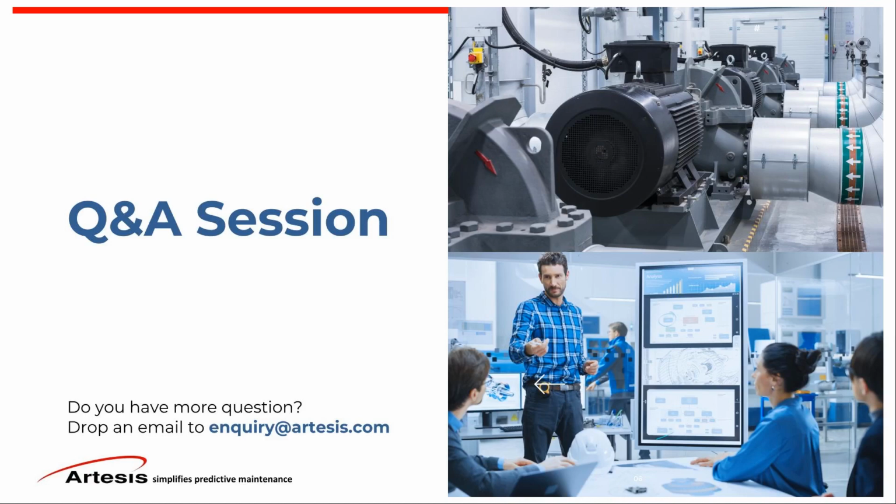Another question here regarding installation for high voltage motors: is it possible to use the previously installed CTs and VTs? That is a great question, actually. I forgot to mention this. Yes, we do require and use the previously installed existing CTs and PTs for medium or high voltage motors.